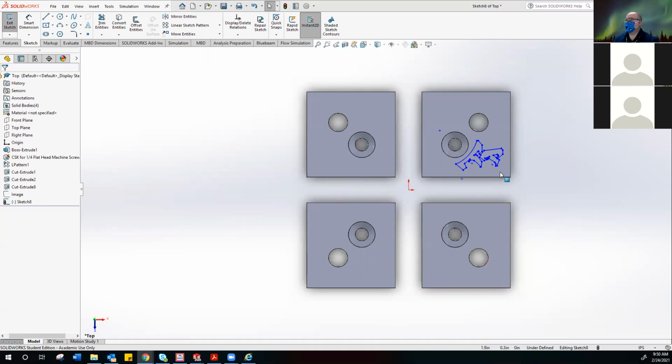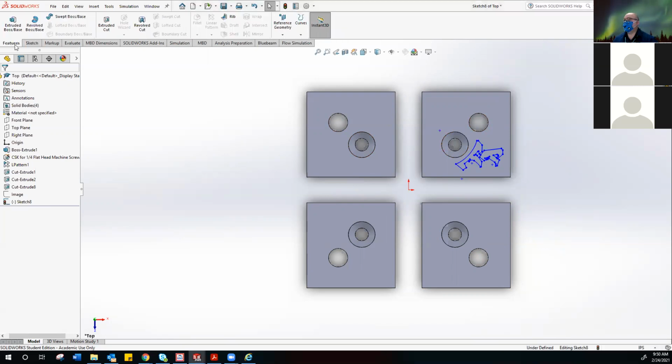So what I'm going to do is go ahead and make my 3D element first. Now, some of you are asking, how do we make it 3D? We can't go up. Remember, your slide has to go back and forth. That's why I showed you earlier. We can only go in to the surface. So it's called embossing. Okay, we're going to emboss it in. So I'm going to go into my features tab. I'm going to use an extrude cut.